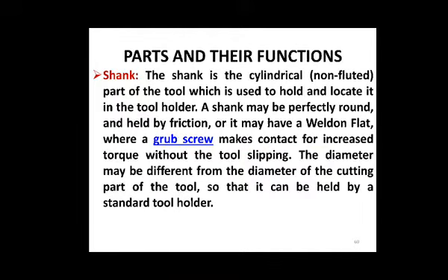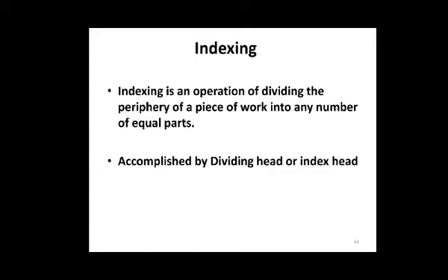Now next we are going to see the dividing head, that is, indexing. Indexing is an operation of dividing the periphery of a piece of work into any number of equal parts, accomplished by the dividing head or index head. So here you can see the principle or mechanism of the dividing head. Here you can see the main spindle, which drives the workpiece.